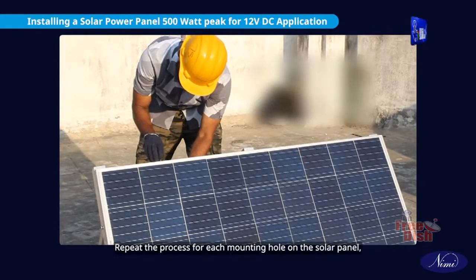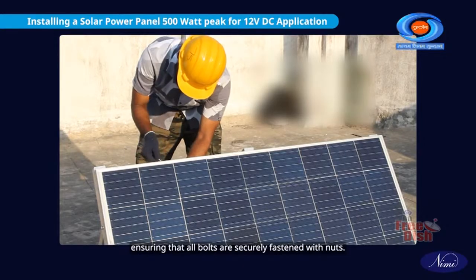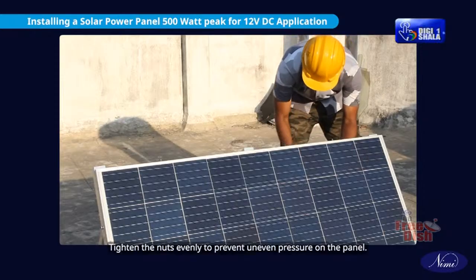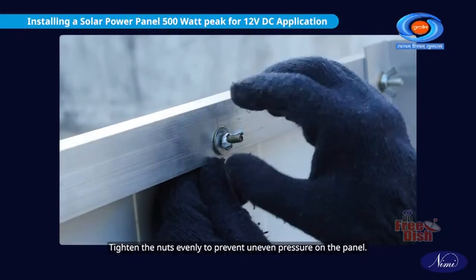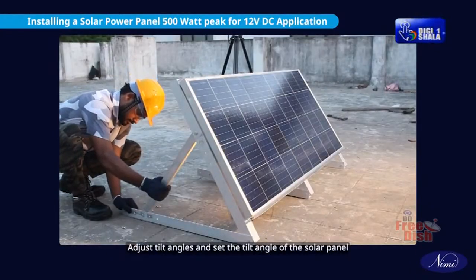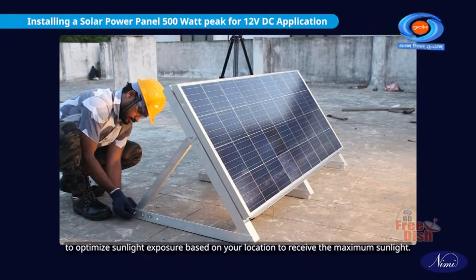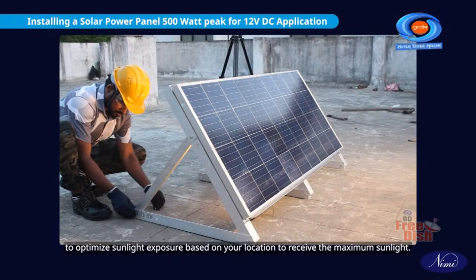Repeat the process for each mounting hole on the solar panel, ensuring that all bolts are securely fastened with nuts. Tighten the nuts evenly to prevent uneven pressure on the panel. Adjust tilt angles and set the tilt angle of the solar panel to optimize sunlight exposure based on your location to receive the maximum sunlight.